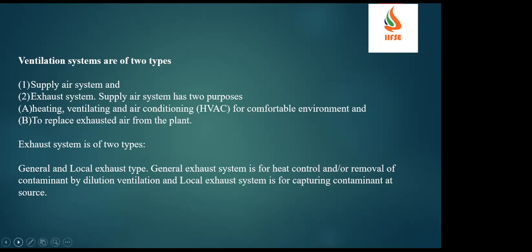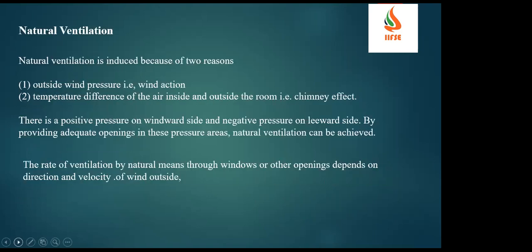Local will be specific to an area where your sources are; wherever the source is, there you are installing your exhaust. Then natural ventilation. Natural ventilation is induced because of two reasons: one is outside wind pressure and the other is the temperature difference. Here you are not using any mechanical aids. You are not using any energy, power, or machinery to ventilate your workplace. It's natural.